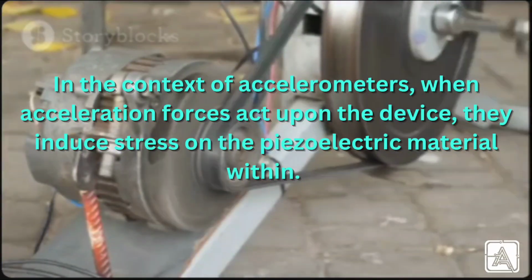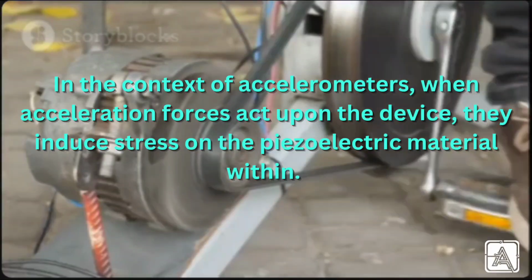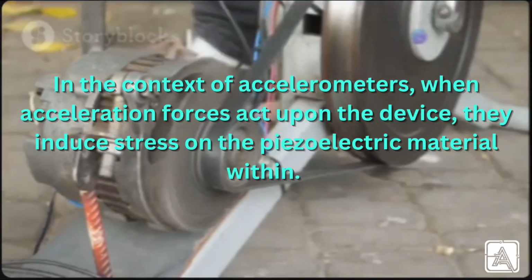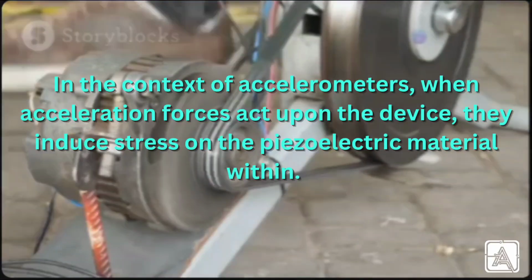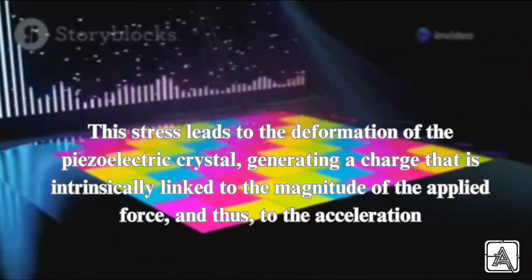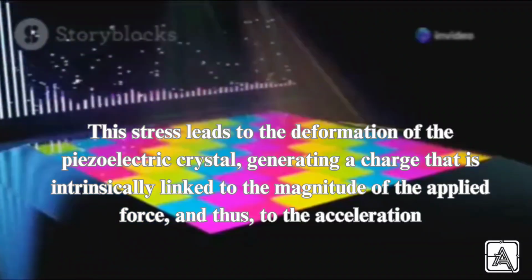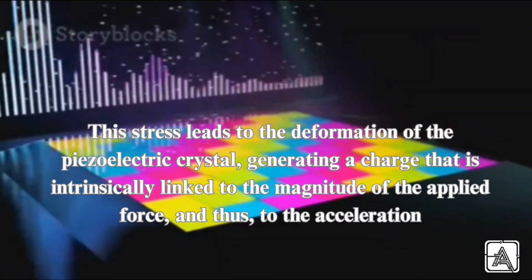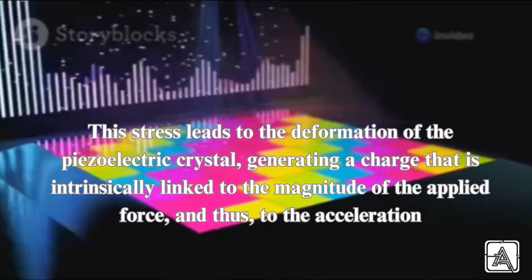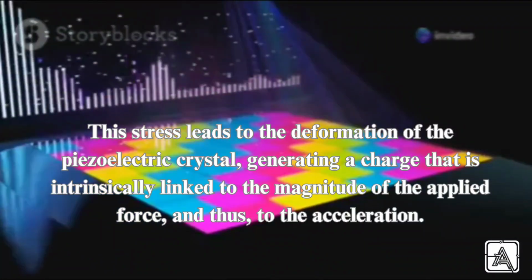In the context of an accelerometer, when acceleration forces act upon the device, they induce stress on the piezoelectric material within. This stress leads to the deformation of the piezoelectric crystal, generating a charge that is intrinsically linked to the magnitude of applied force and thus to the acceleration.